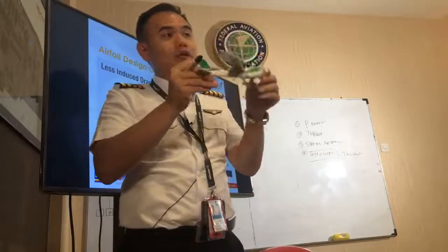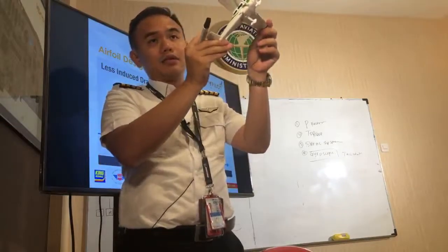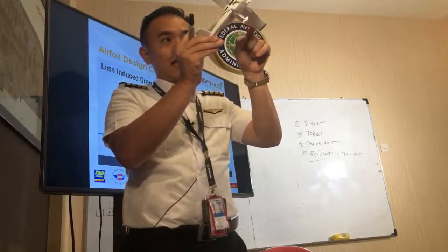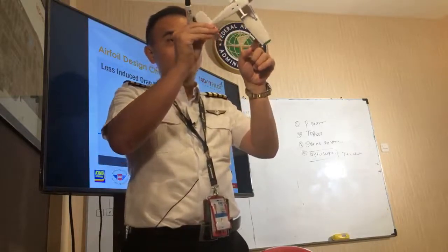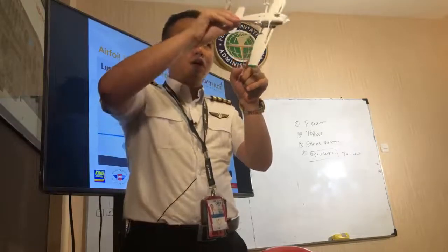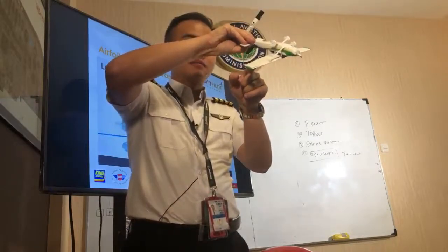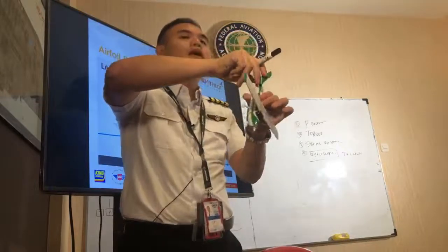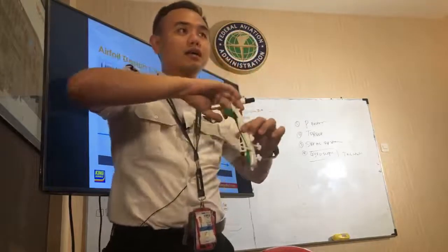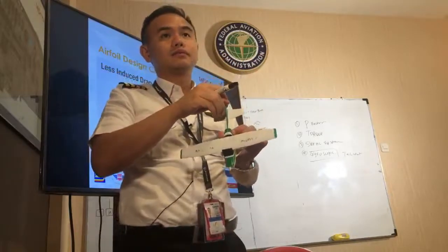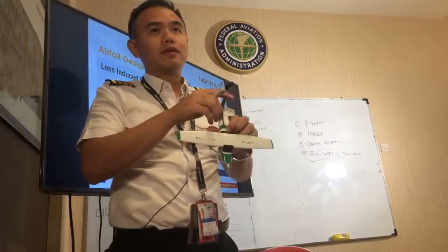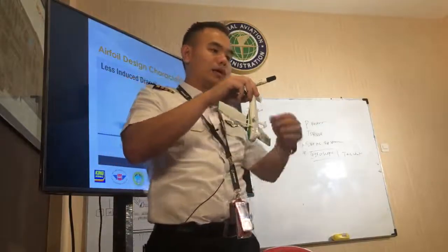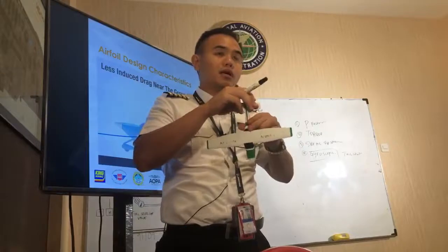Let me repeat. Higher angle of attack, exceeding it, airflow separation. The left wing stalls first. You have yaw, you have roll. So what is this? Spin. This is a spin. How to recover? There's PARE. What is PARE? Power idle. What else? And airspeed.